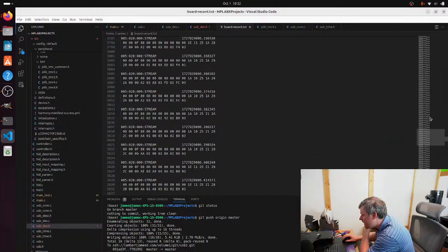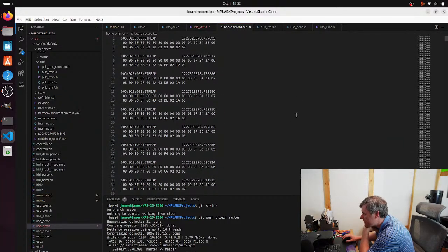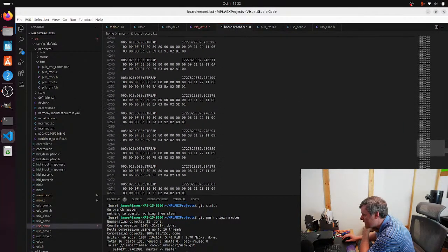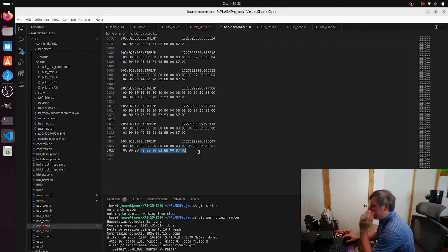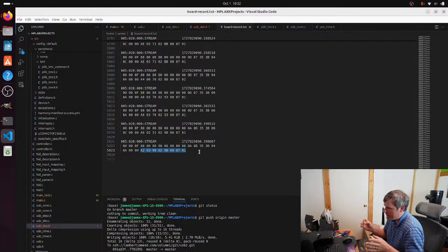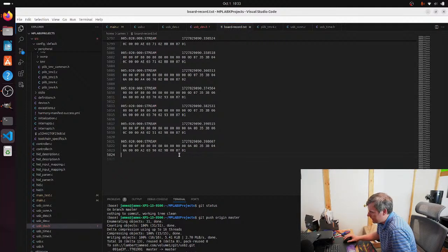All right, so here are the bytes that I wanted to decode. Really, I could just code up a quick script to take the data here. I think what I want to do is take all of the 10 bits that are being sent in the 4 groups of 10 bits, concatenate them all together and see. It's possible that there's 3 values of information from the accelerometer being sent across those 40 bits, and the way they packed it was weird. That's my theory as to what's going on here.